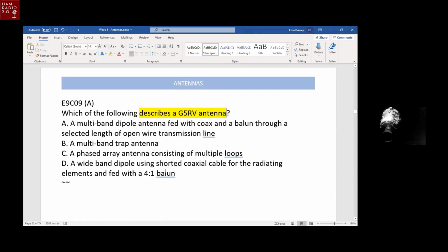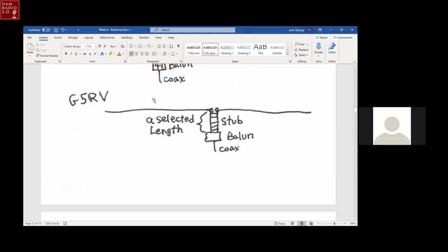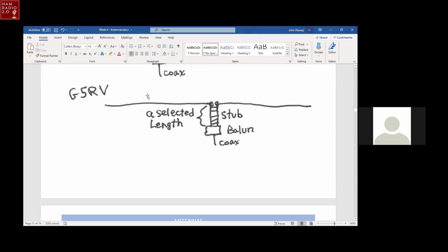How long's the overall length then? Or is that band dependent? I'd use a half wave on 20 meters. Oh, it's a half wave. I haven't built one of these. You got any information about how long it is? I'll have to dig it out and measure it. I can find out before next week. Well, is it a half wave, a quarter wave? Obviously by frequency it's going to vary. They're quarter wave elements on each side. Quarter wave on each, okay. And if I remember right, overall they are cut for 20 meter also, and then it'll work on 40 all the way down. They do make one that'll work on 80, but it's huge. That thing is a beast.